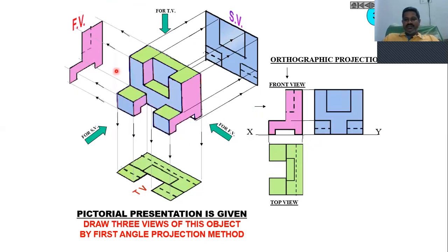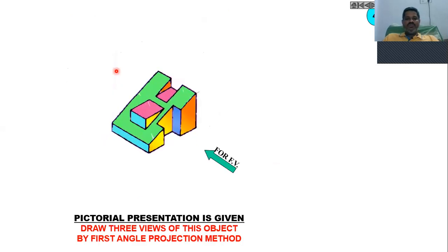This is what the front view, side view, and top view of the mechanical component, which is given in this figure, look like. Now, let me move further to see one more block, and this is my front view. Okay, so if we look at this figure from this side, you will find this face, and this face, and this face also you will find, and this edge in front side and back side edge will coincide with each other. Similarly, the front edge and back edge will also coincide with each other. And finally, you will get a dotted line at this location, dotted line at this location.